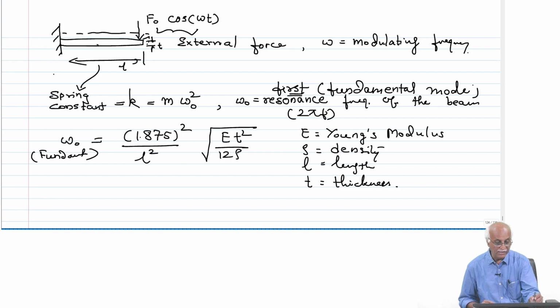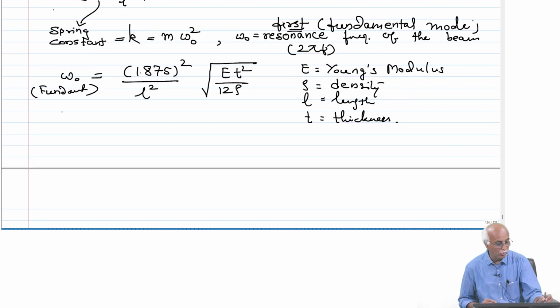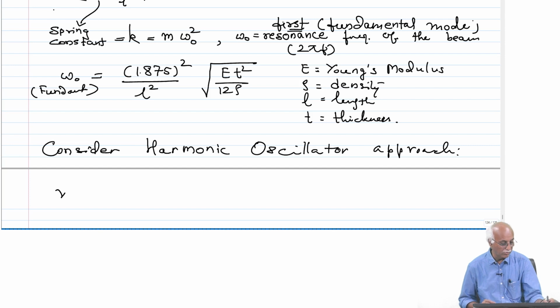Of course, the cantilever beam under this sinusoidal force, the governing equation, it is nothing but a harmonic oscillator. So we are considering the harmonic oscillator approach, that this cantilever beam acts as a harmonic oscillator.